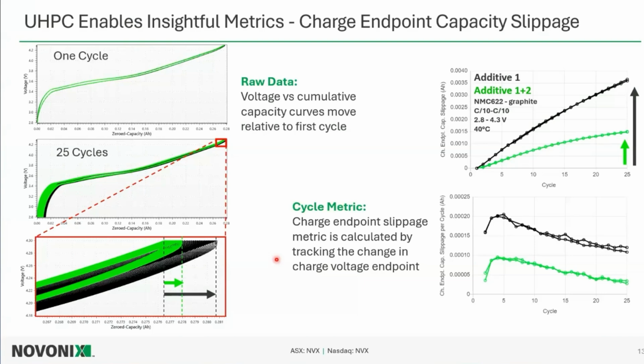So I'm going to go back up to some of these slippage-based mechanisms and really look at what they mean in practice when we're looking at our data. So if we think about one cycle of a cell, looking at cumulative capacity over the x-axis here versus voltage, so not zeroing once we reset charge and go to discharge. If during our charge cycle, we count these additional mechanisms happening, these additional electrons that are going to go through our circuit due to these slippage mechanisms, we're going to count a little bit more capacity than the lithium we're actually moving across the cell.